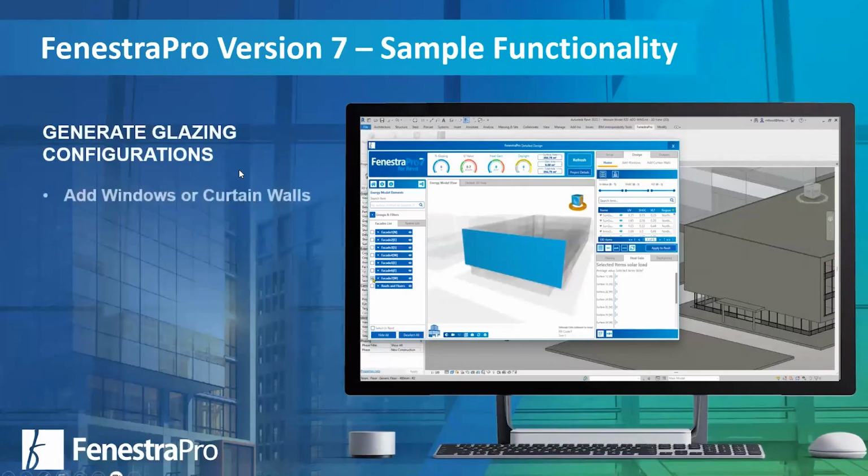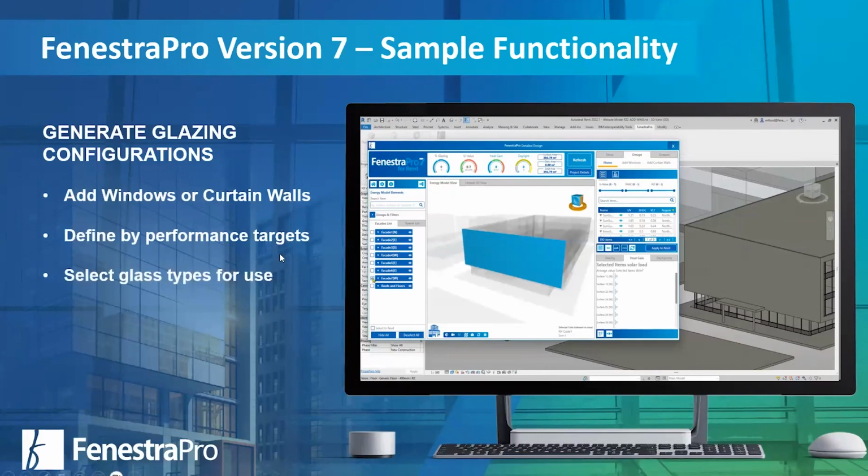We can generate configurations, and they could be adding windows or curtain walls. We can define that by configuration or by performance targets, and select different types of glass and look at how we can meet certain performance targets of the building based on various alternating glass types. So an example there would be, if I go with a solar control glass, I might get 6 punch windows on a given space, whereas if I'm using a standard glass to achieve the same results, I might only be able to use 2.